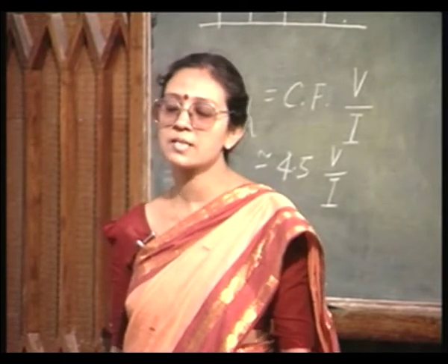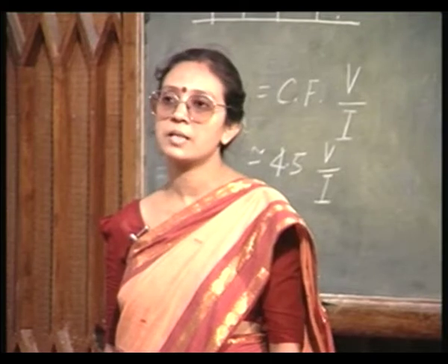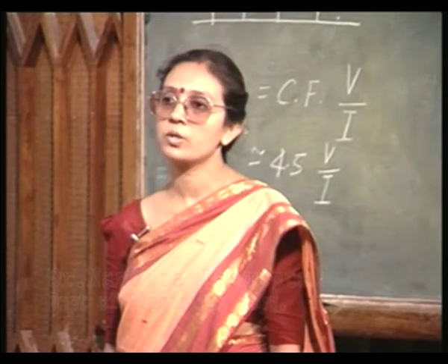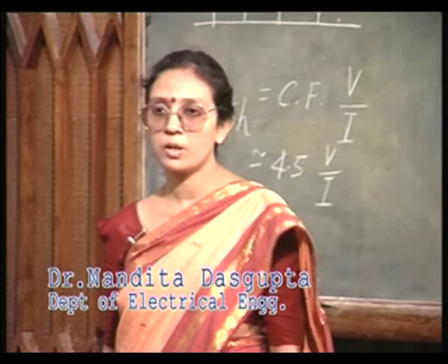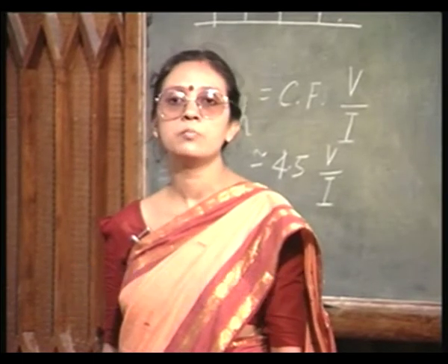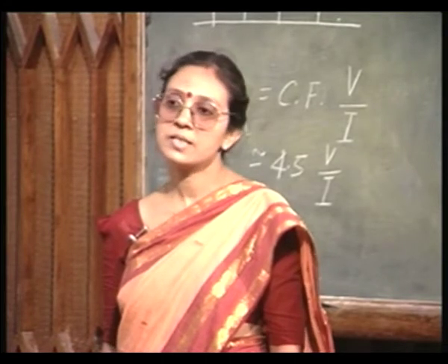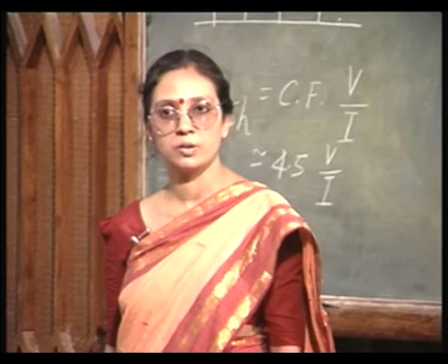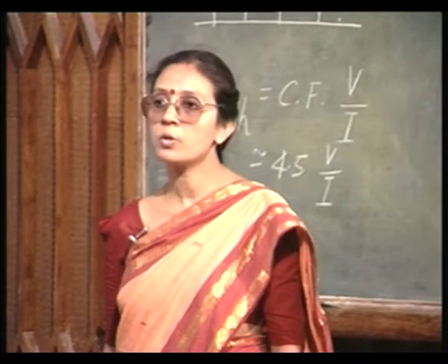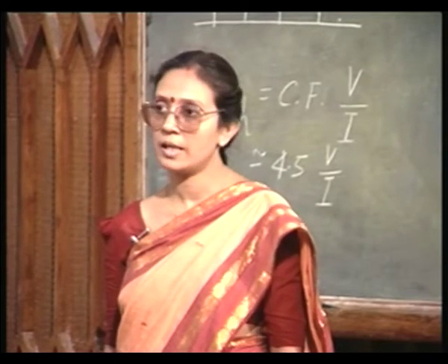Since this dx is very, very small, you can approximately consider that the doping concentration is nearly constant in this very thin region. So, what you know is the product mu into n. Okay. Now, mu versus n plots are also available, and you know mu times n, so you can find out what n is going to be.